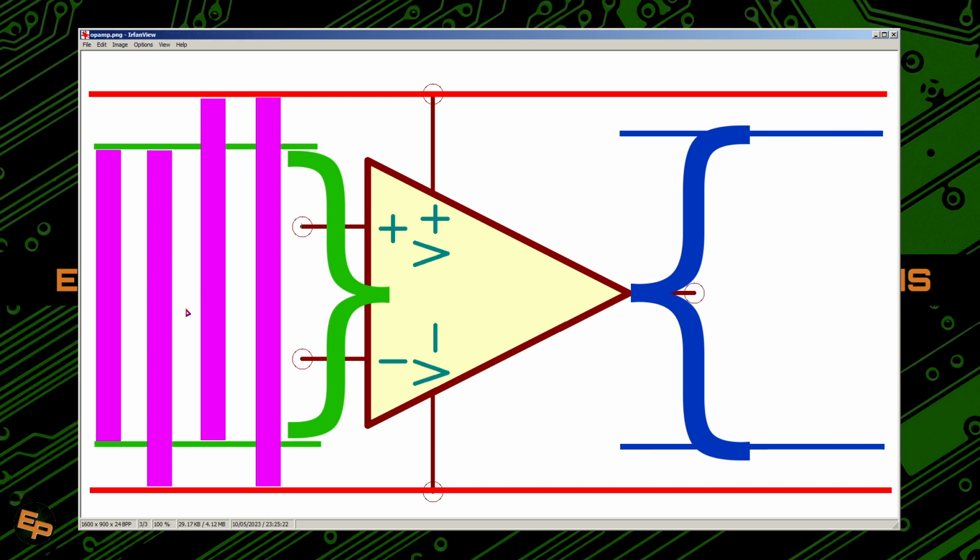And then in the second experiment, I'm increasing the amplitude of the input signal so that the op-amp will try to make its output go above these limits. Of course, it won't be able to do so, but that's when the op-amp will have certain transistors go into saturation and cause problems.